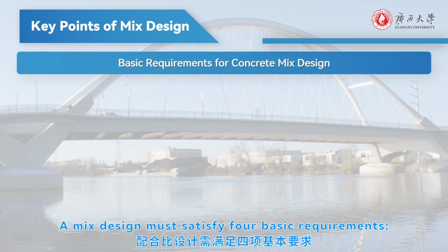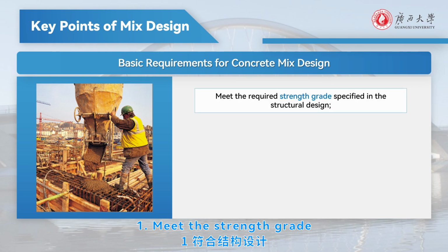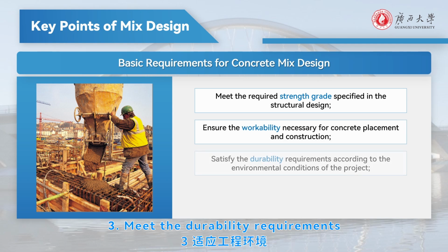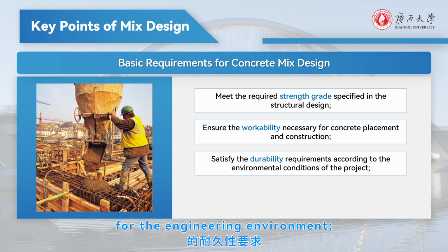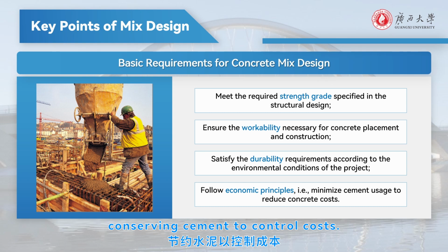A mix design must satisfy 4 basic requirements. 1. Meet the strength grade specified in the structural design. 2. Have the workability required for construction. 3. Meet the durability requirements for the engineering environment. 4. Follow economic principles, conserving cement to control costs.